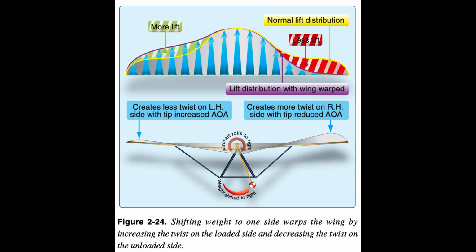Stability and moments. A body that rotates freely turns about its CG. In aerodynamic terms for a WSC aircraft, the mathematical value of a moment is the product of the force times the distance from the CG, moment arm, at which the force is applied.